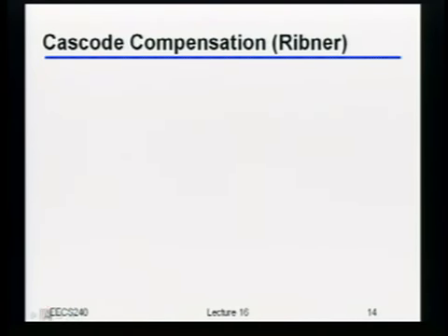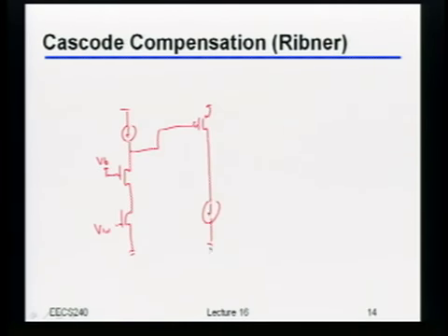So the basic idea here is actually pretty simple. Let's say, and I'm only going to draw the single-ended version here, but you can imagine I could do this with a differential as well, that's my input. Let's say I have just some bias voltage right here. So I have a cascoded first stage. And actually, that's not a resistor here. Sorry, I'll draw that as a current source. So this is just my OTA for the first stage. Okay, and so this would have been my normal two-stage OTA.